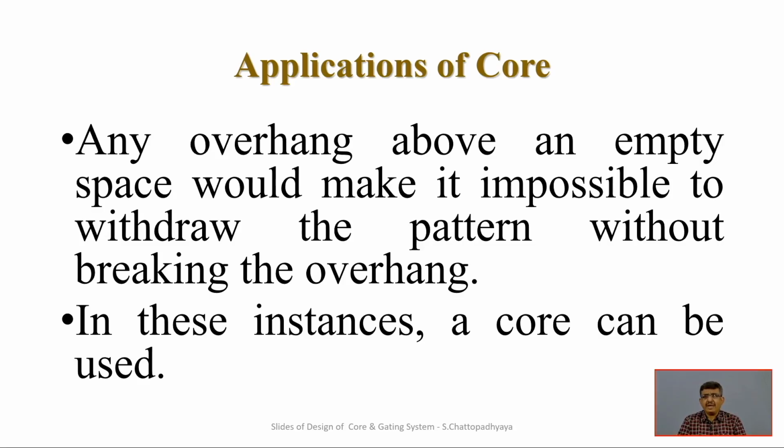An overhang above an empty space would make it impossible to withdraw. If it is an overhang, you cannot withdraw the pattern without breaking all those things. So what will be there? The core will be placed, maybe with some pins and with some very specific device called chaplets, in order to position those cores in these overhang positions. So the core is indispensable in those kinds of cases.